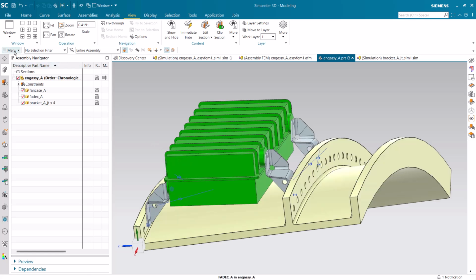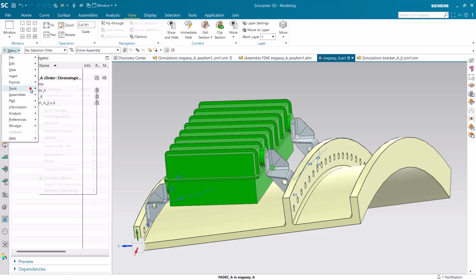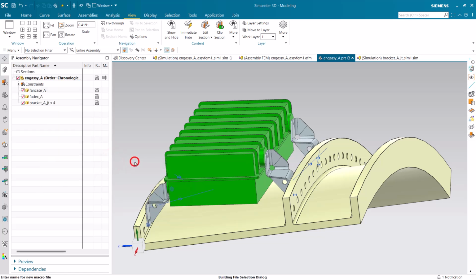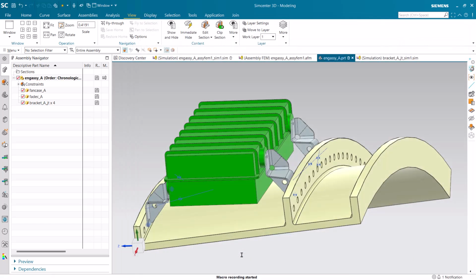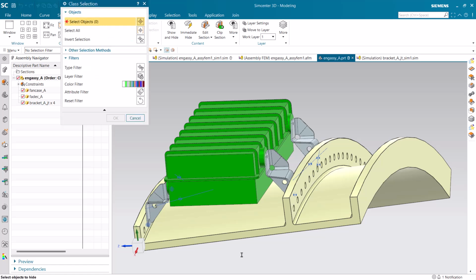Now I've done a Control-Shift-U to show all, and because those 3 commands might be a little bit tedious after running them several times, we can create a macro that will run all 3 for us. So here we'll start recording a macro, and I'll do Control-Shift-U, that will be captured in the macro, and then I'll do Control-B, which will also be captured in the macro.